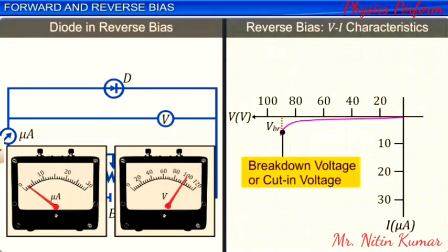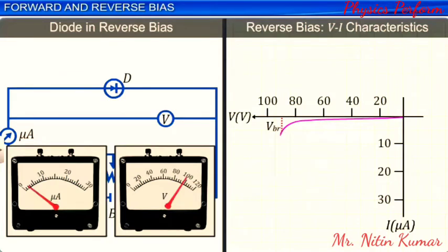When the applied diode voltage becomes equal to the threshold voltage, the current in the circuit increases suddenly to very large values, causing a lot of heat to be produced in the diode, and hence the diode can get damaged unless we adopt some precautionary measures. Typically, the threshold voltage is nearly 0.2 volt for a germanium diode and 0.7 volt for a silicon diode.